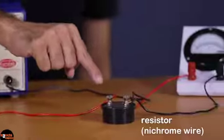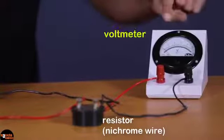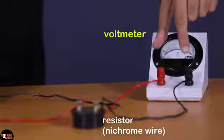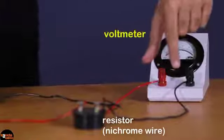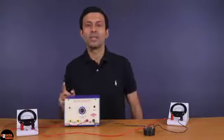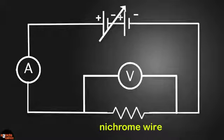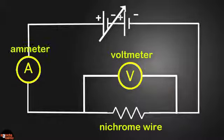To measure the potential difference across the wire, we will use this instrument called the voltmeter. As you can see, it is connected in parallel to the wire. If you draw the circuit diagram for our setup, it will look something like this. Here is the nichrome wire that is inside the black box. The voltmeter, which is marked with the V symbol, is connected across the ends of the wire. The voltmeter is connected in parallel. And the ammeter, which is marked with the A symbol, is placed in series with the wire.